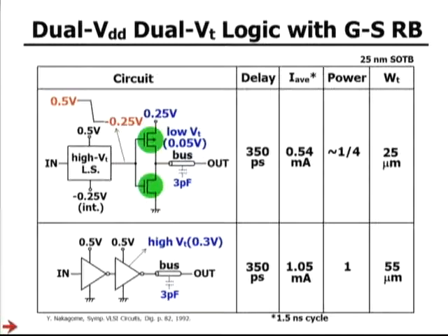And when it is off, subthreshold current is reduced due to the gate source reverse biasing. This is also the case for NMOS. When compared with the lower conventional 0.5 volt high VT CMOS driver, for a given delay, average current is almost halved at a halved power supply. Thus, power is reduced to 1/4. Note that necessary total channel width is also halved.